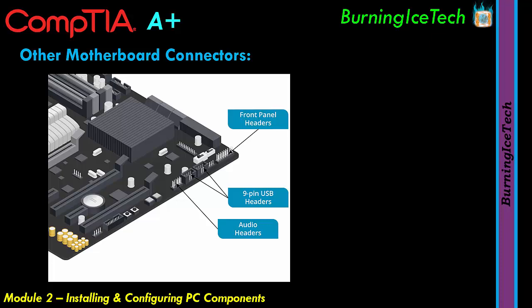So what you can actually go and do, and I do not advise you to do this because if you don't know what you're doing, you can blow your motherboard. If you take a very, very small flat screwdriver and you touch those two PWR points with one another, basically allowing it to make contact with one another for a brief second, your PC would actually start. It's kind of like jump starting a car. You're jump starting a PC.